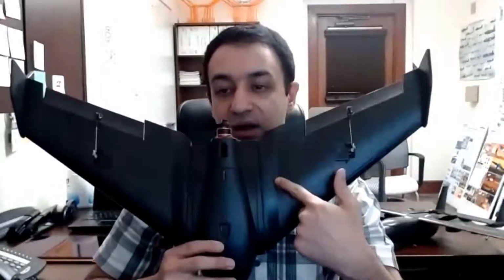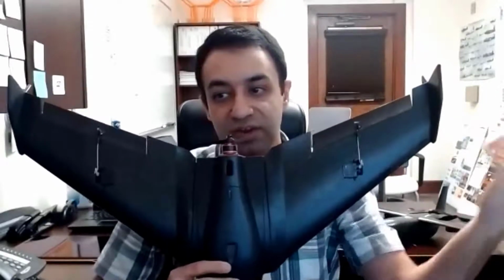If I connect a quarter of the wing here to the quarter here, this would create an angle with the horizontal reference that I have. So in this case, my drone has a higher value of the sweep angle. It has less lift coefficient, and it should fly faster to get enough lift.